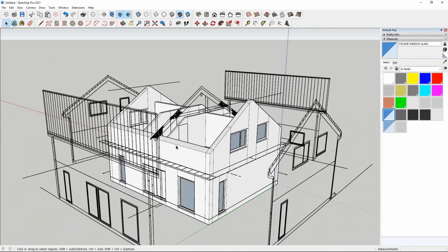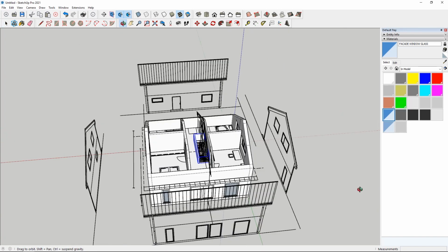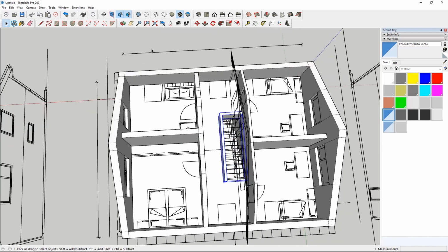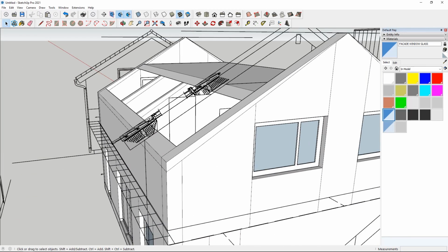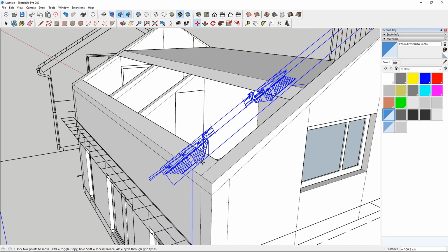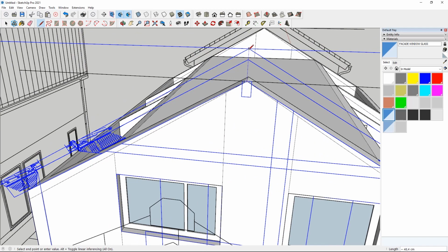Using the ground plan and the section plan, we can go to the next step and model the roof. Here we will only model one side of the roof, since the roof and the window placement is symmetrical over the center ridge of the house. Go ahead and move this section over for easier modeling. We'll draw out the outline of the roof, following the section plan, just as I'm doing here.